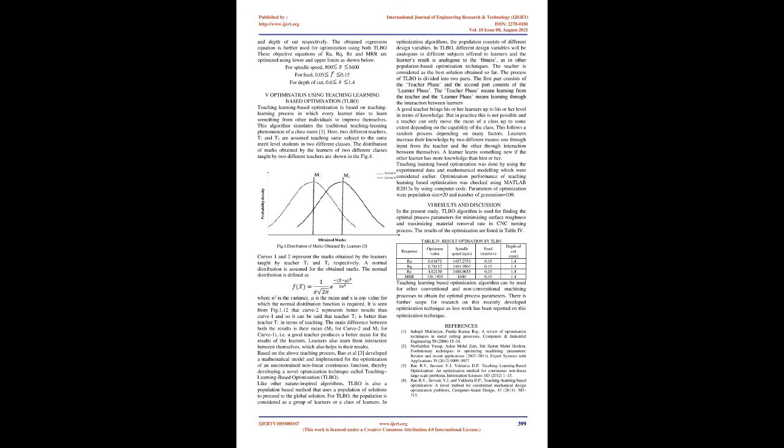Roughness measurement has been done using a portable stylus type surface roughness tester, the SJ210 model of Mitutoyo make, shown in Fig. 3. It is a shop floor type surface roughness measuring instrument, which traces the surfaces of various machine parts, calculates their surface roughness based on roughness standards and displays the results.